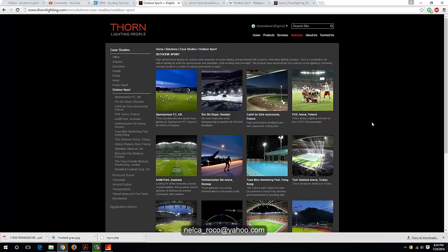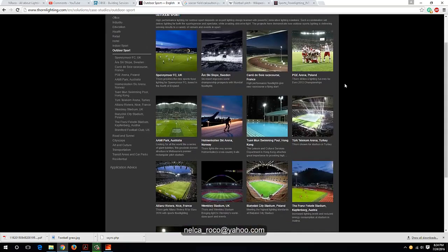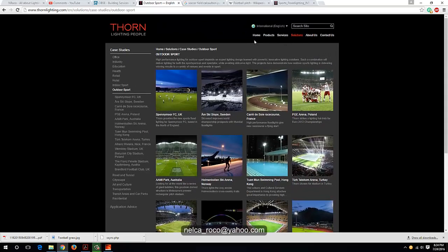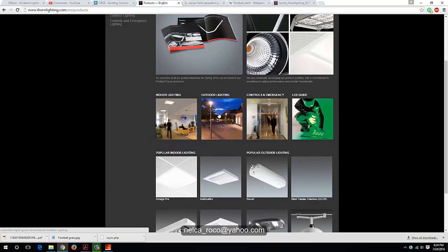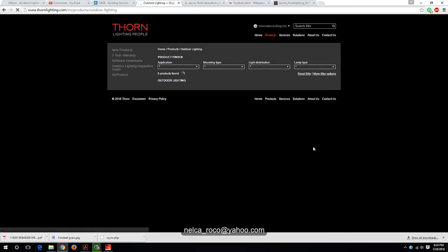Thorn Lighting is, I think, one of the best suppliers or manufacturers of luminaires in sports lighting, so I can use the fitting of Thorn Lighting. If you go to the website of Thorn Lighting, go to the products, then go to outdoor lighting.